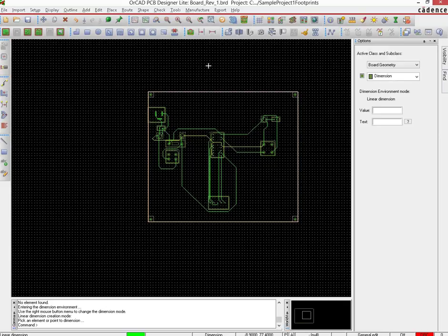Now that we are almost done with the entire board setup in PCB, what we need to do is add some more information in this particular board drawing file so that it is more representative of the design. Information like how wide the board is, how long it is, and then information like the drills that are required for the holes that are to be drilled on the board and their diameters and how many holes there are.